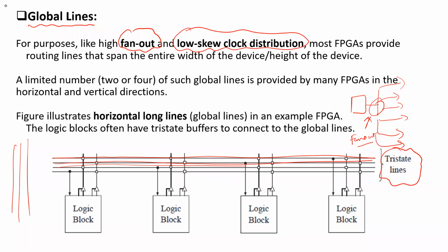Okay, so these are the FPGA components. We have studied the first one, the CLB, configurable logic block, which can be operated in three modes of operation. The next one we can call programmable interconnects, which we have also studied. Now we are going to see about IO blocks.